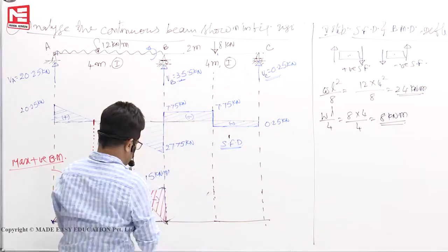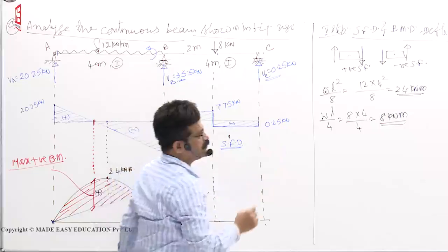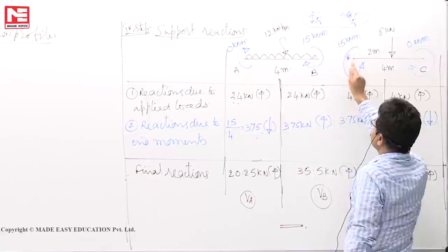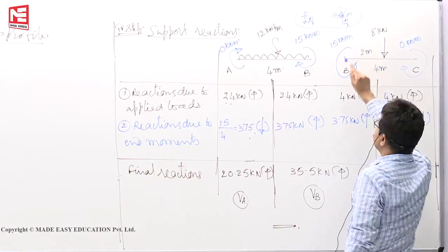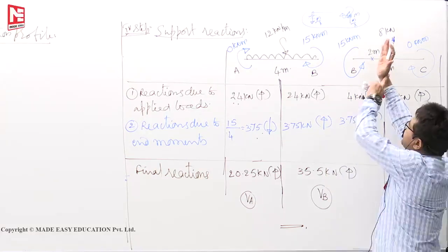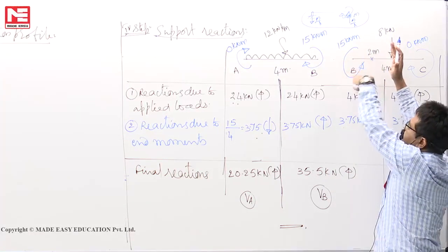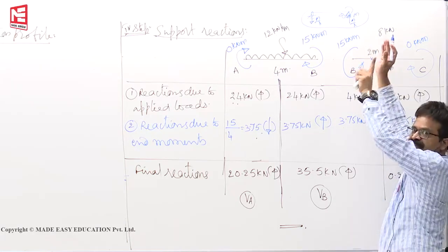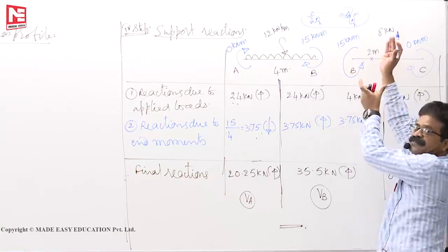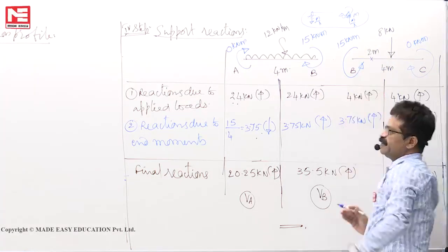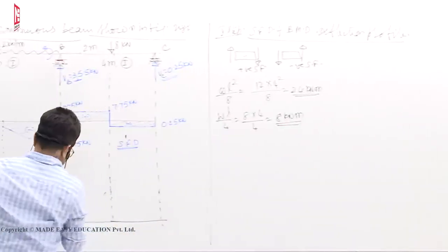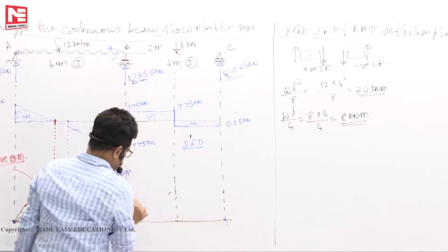First you show this one. If the end moment you see here, you cannot stand here and look right side, because section right side anti-clockwise we should not read it, because you cannot stand in the air. So you must stand here. Section left side anti-clockwise. This is actually minus 15 as per the end moment sign convention. Bending moment sign convention, see, section left side anti-clockwise will hog the beam. So minus 15, and here it is 0. Here 15 already have drawn. Here it is 0. So draw a straight line.